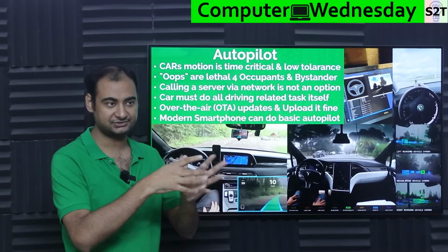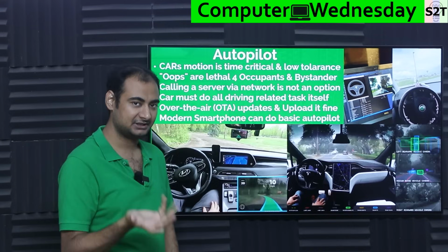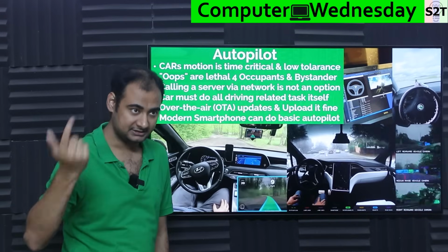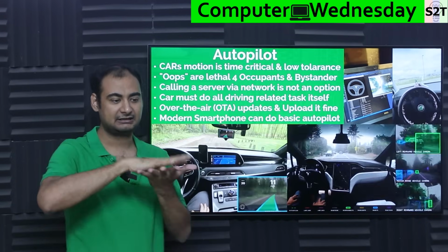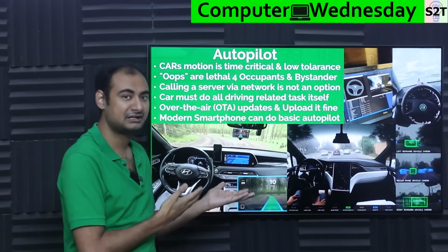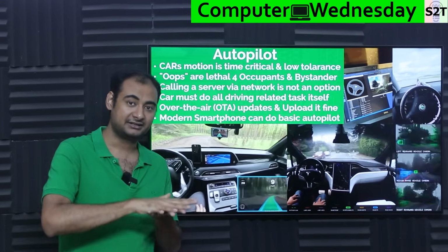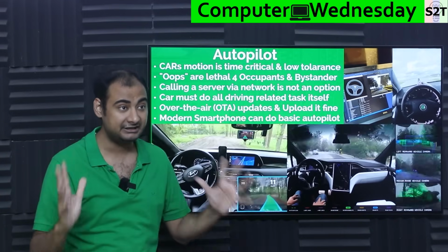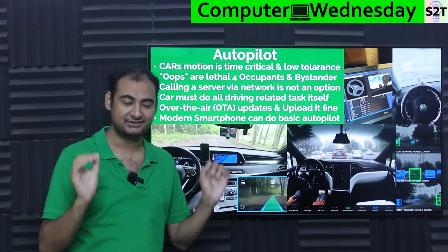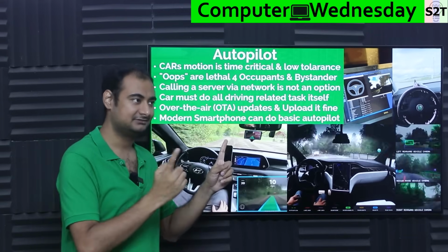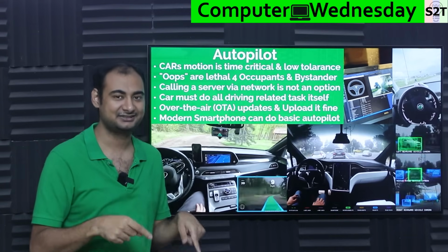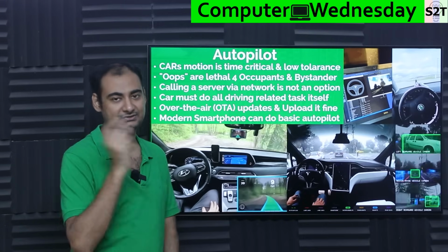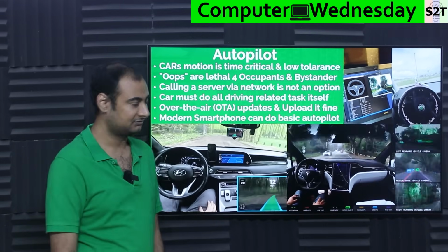And let's say the place that you are using, they create a rudimentary optical map of it. That optical map goes into basically a super cluster. Now here's the deal. Multiple cars in the same area are doing that. So they are creating a layered map, because again, they do not have LiDAR, so precision is very sloppy. But if you have 50, 60, 70 cars going through there and overlapping all the data, now you have very high fidelity, high precision, real world data. That data is so high end that from a car's point of view, it cannot tell the difference whether it's running in real life or a simulation. Now they run their AI agents that are doing the training. So that can be done, no problem with that.